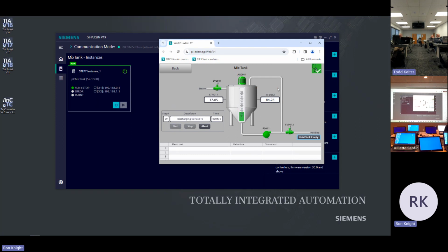First of all, we need to pick a spare IO point. That was their stipulation: add that high level switch, but you need to add it to an existing I/O rack, to an existing digital input module. So we need to go find a spare I/O point. We need to create an alias for level switch 13, and I want to do it object oriented. I want to create a user-defined type that'll allow my HMI to monitor any level switch we're ever going to add.